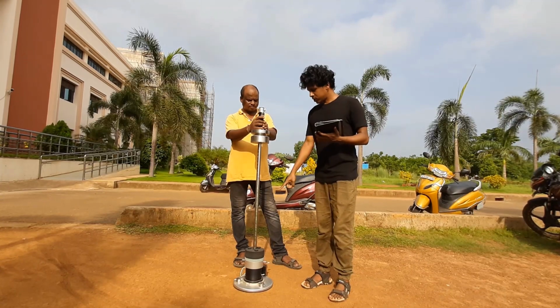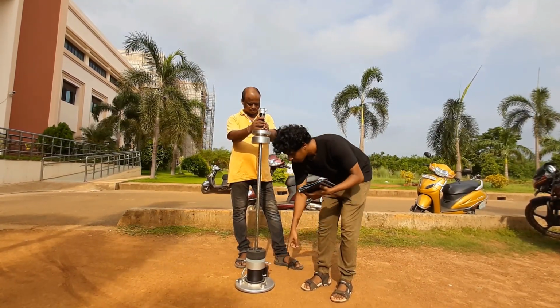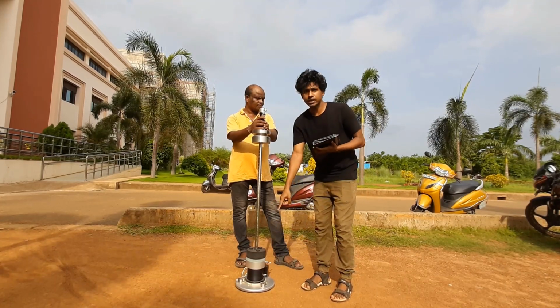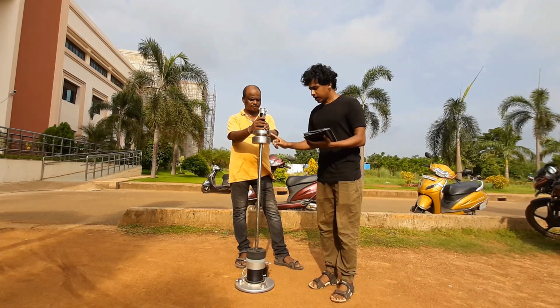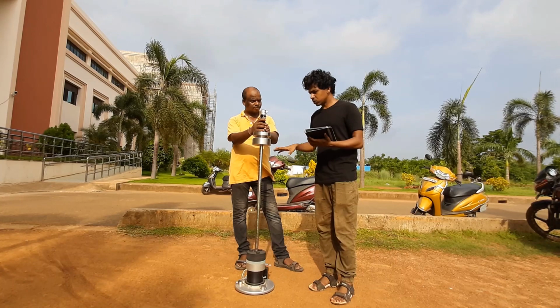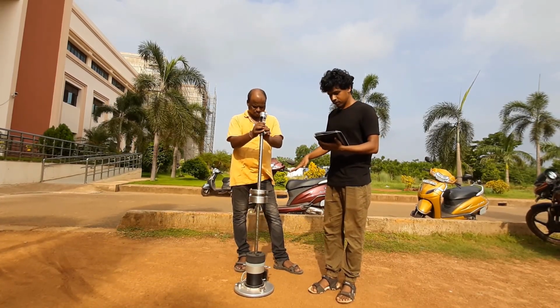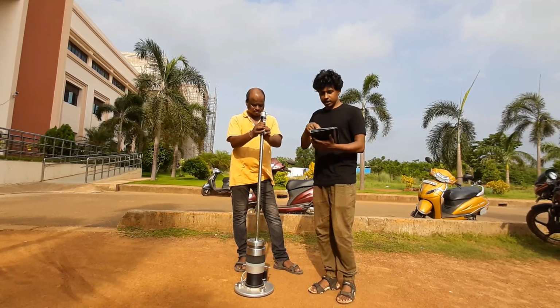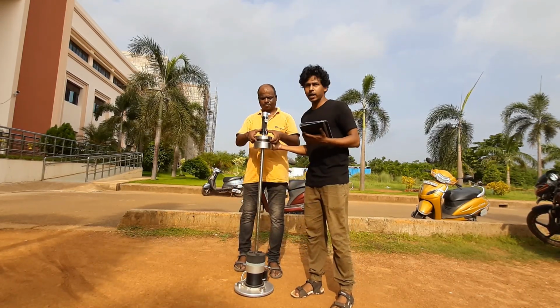This is the LWD setup. Initially, we will attach the bottom plate on a plane surface, for which we have to find the modulus and deflection value. Then this is the 10 kg weight. Actually, the reading will directly come through Bluetooth in this tablet. So first, we have to let the weight down. The reading, now you can see the reading on this tablet. Then again repeat the procedure. Please do it for 5 times for one location.